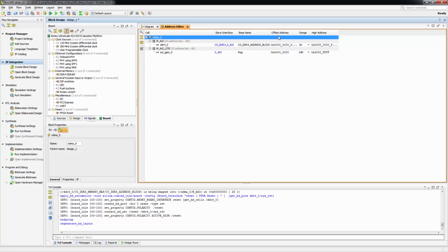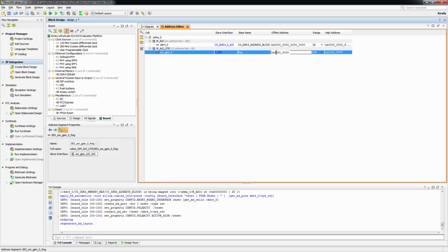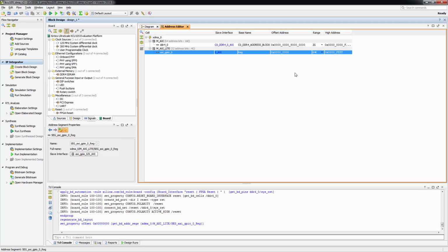Here we'll go ahead and look at the address map, and we see that the DDR memory is mapped to address 8 million hex, and we're going to go ahead and add our GPIO just to address 0, and that will match up because we left our address translation register for that AXI Lite interface to 0. So anything that hits that bar will go to address 0 or whatever offset has been set to.